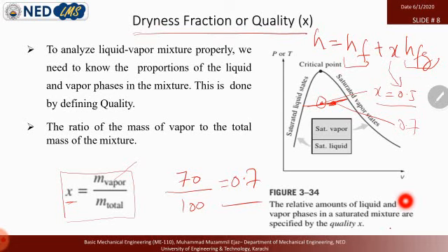So it is very harmful for steam turbine blades, because turbine blades run at very high RPM, and the steam flowing through the steam turbine has very high velocity. So when water droplets at very high velocity hit the blade of the turbine, they erode that metal.